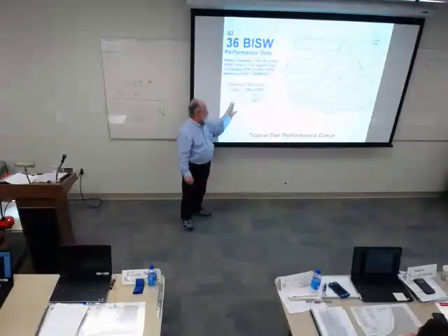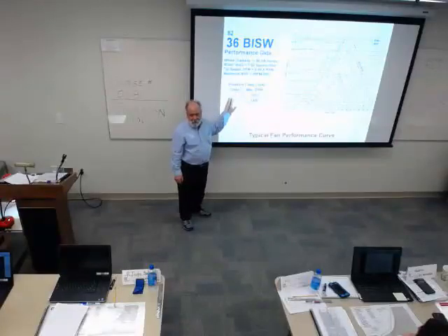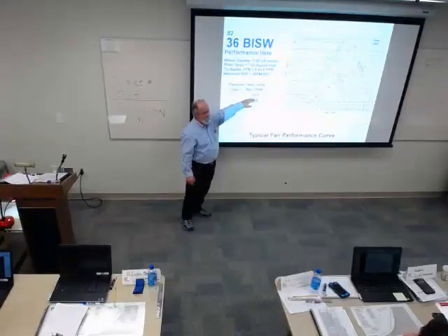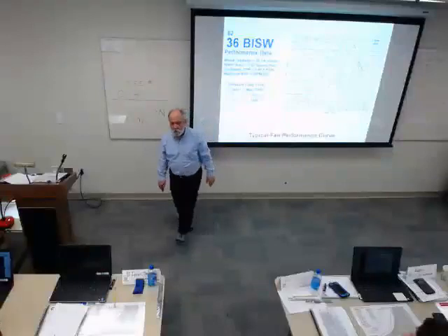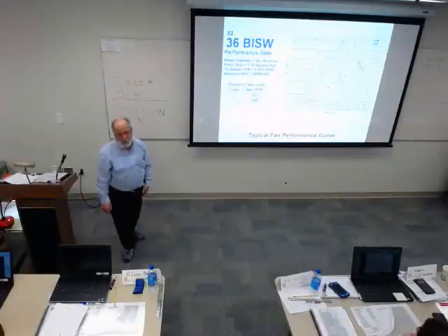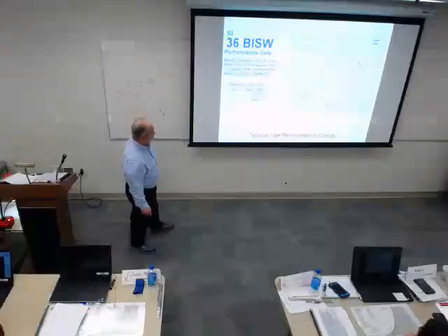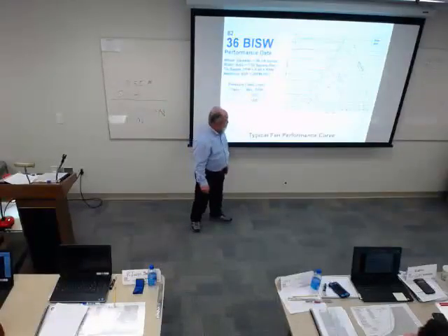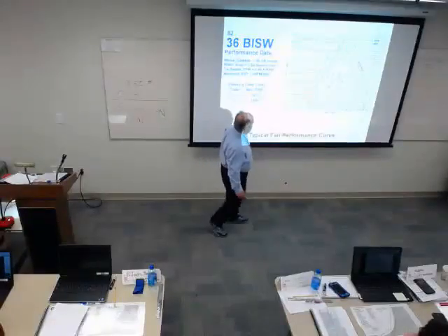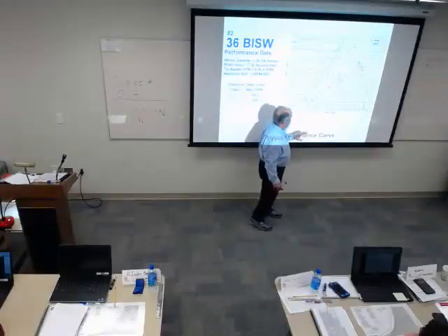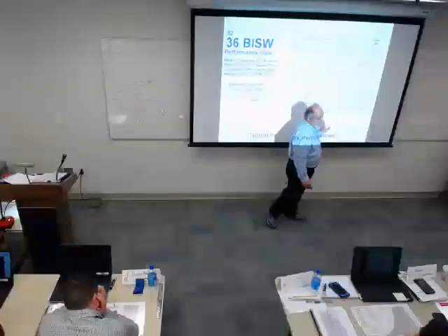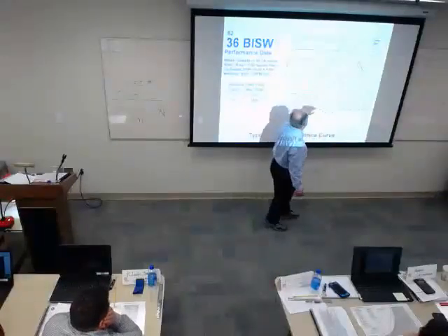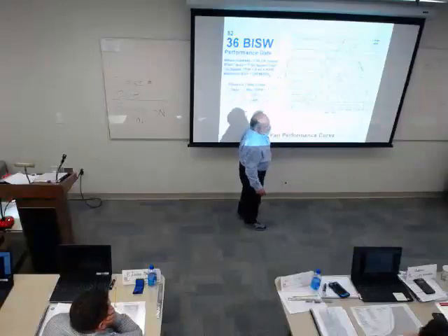Pressure class is kind of important, because a lot of times if we can't make the pressure that we need, we'll speed the fan up. Well, for class 1 on this fan, 1073 is your max RPM. Go over that, and you run the real risk of everything blowing up, because they will come apart. Class 2, its limit is 1400 RPM. Just quickly go through what we're looking at here. We've got horsepower lines, those are the red ones. We've got the CFM, multiply times 1,000, and then here is the static pressure in inches of water.